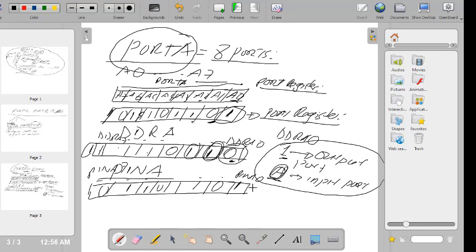But I want to mention here, when do we normally use the port register? Now I want to mention the pin register, sorry. The pin register is read-only. You can see here the data direction register and the port register are read-write, meaning that you can write information to it, and you can also erase certain information, and they can also read from it.